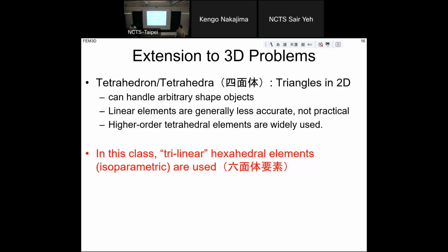Okay, so good morning. Let's start the second day. Yesterday, we started with a very fundamental part of the finite element method and 1D code, including algorithms for iterative methods, and we also learned about the method for sparse matrix storage, the CRS format, compressed row storage. And in the last part of yesterday, we started 3D.